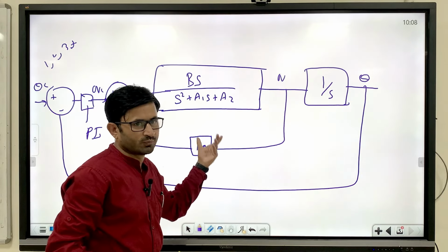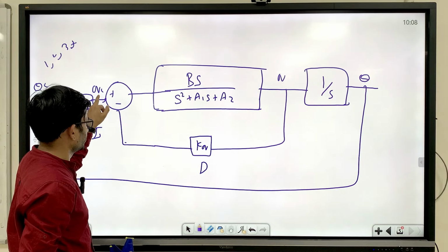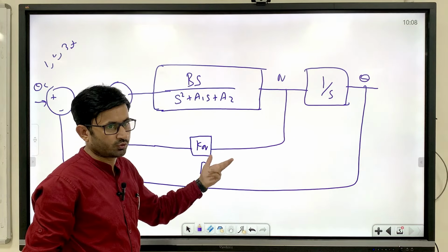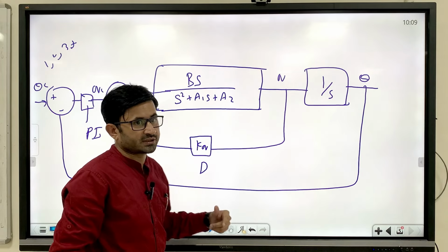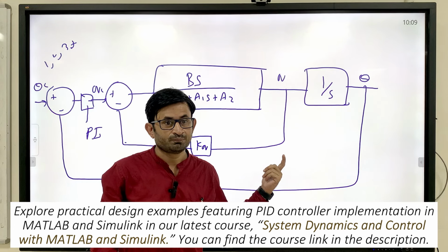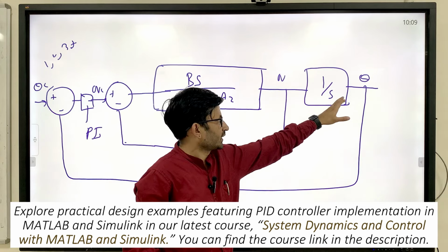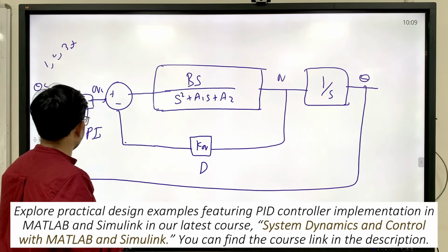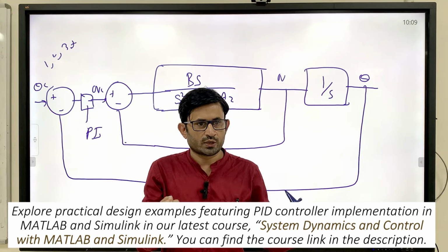So to start with the innermost loop, you have to get the q first, with qc equal to 0, in order to stabilize the rate loop. This is called the rate loop. And by changing the gain you can change q by using root locus. Now you have a second order transfer function, right? Once the stabilization is done, you may integrate this in order to get theta, close the loop again, and by changing the P gain you can get the desired response you want.